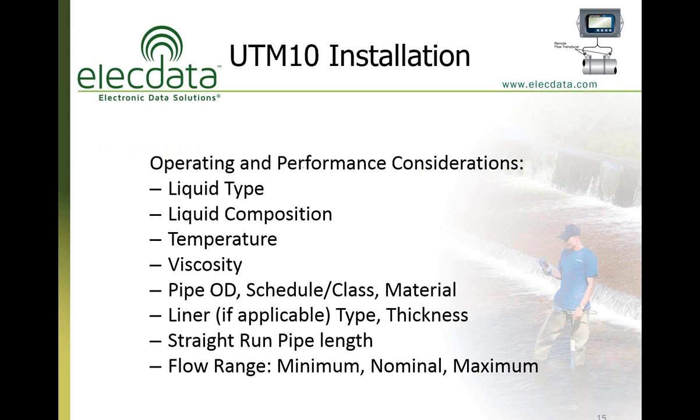We'll now discuss the installation considerations of the UTM10 flow meter. Some of the things that you're going to be prompted for, either through the software or through the keypad interface, are the liquid type, the pipe outside diameter, the schedule, class, and the material, and the liner, if applicable. You'll need to know the type and the thickness, and then account for straight run pipe lengths, which we'll get into in just a few seconds, as well as the flow range: min, max, and nominal.